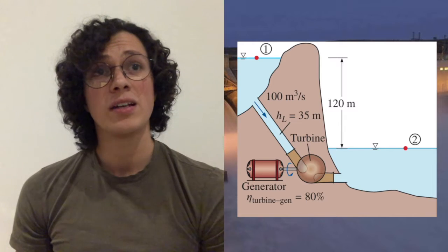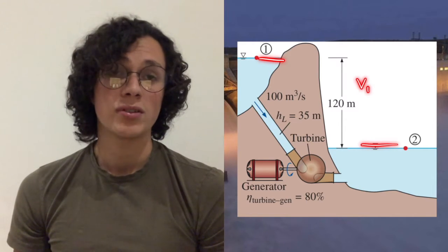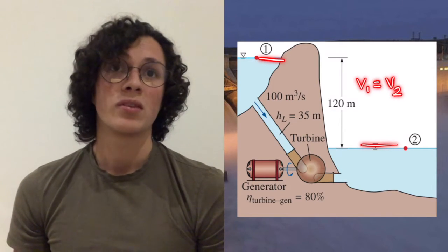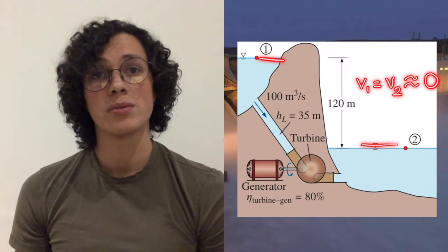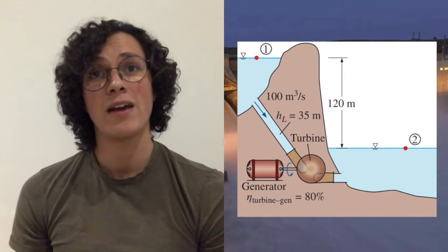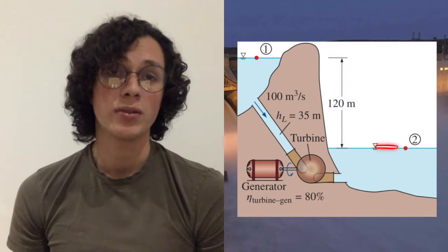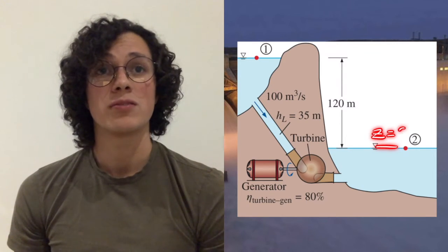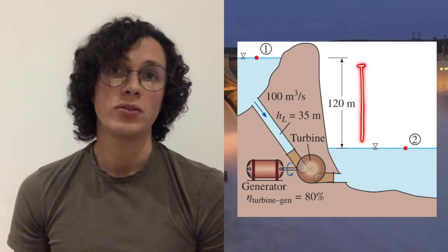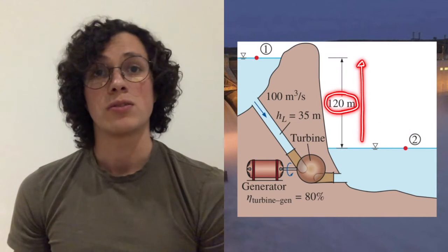Likewise, we can eliminate the velocity term on both points, as these are negligible due to the really slow and barely noticeable change that the water level will have in both points. And finally, we set the elevation of point 2 as 0, so that the elevation of point 1 in relation to point 2 is now the difference between these 2 points.